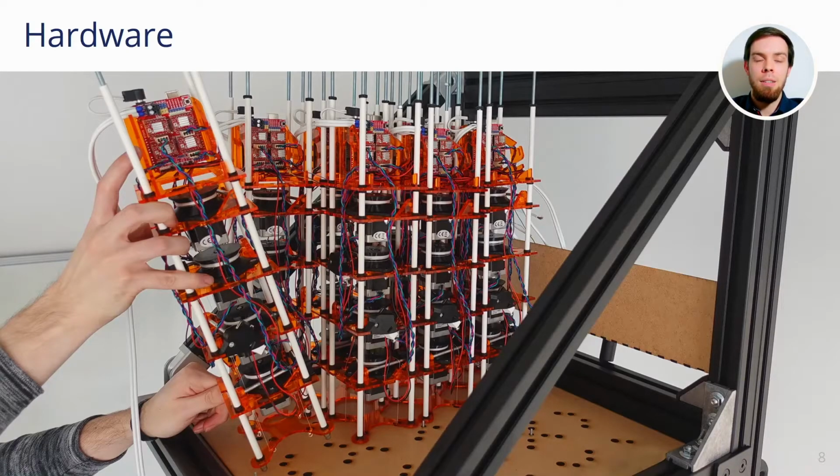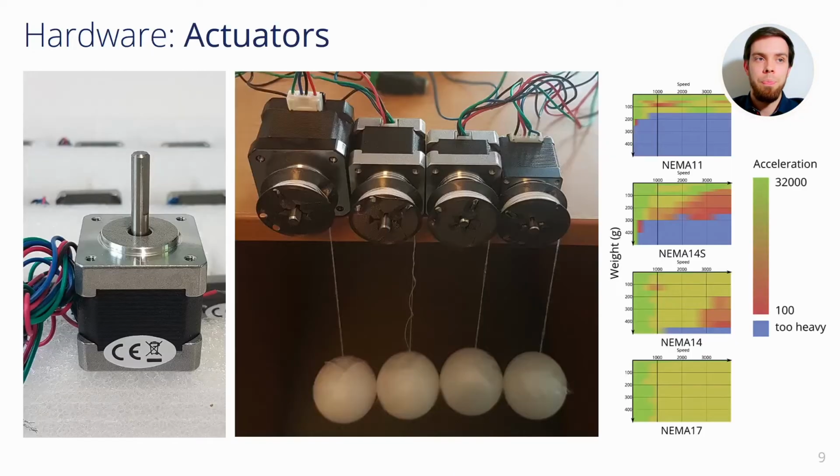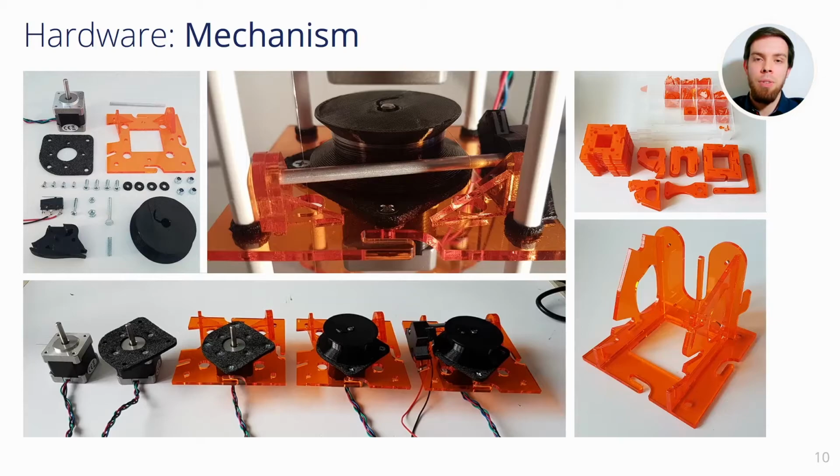Based on these design considerations, we iteratively designed the physical components of our toolkit. We aim for a modular structure to facilitate the exploration of situated use cases with different physical setups. Additionally, we kept fabrication as simple as possible so that researchers can easily rebuild our toolkit. We began by testing different actuators and went with stepper motors due to their fine granular actuation. During initial tests, we studied their properties to infer precise position control for our tailored firmware later on. After committing to NEMA 14 steppers, we iteratively developed space-efficient mounts.